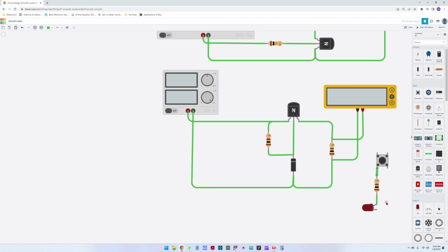Okay, and let us connect this to the rest of the circuit. So we're just pushing everything back to the anode of the Zener diode, and then we're connecting this terminal to the output so that we can switch the load. Okay, let us start the simulation.